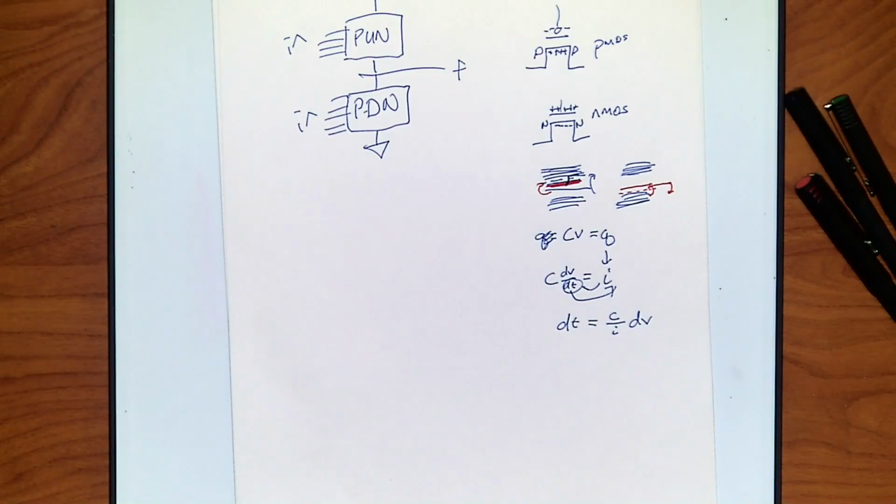Sounds like a weird question, but I want to get something. I don't want to use P1 transistors. Then I use... okay. What's its disadvantage? Yeah, it doesn't transfer the power. So I'm going to get a huge drop on these. It's very inefficient, so I really don't like that. That means I'm generating more heat for no benefit, because I'm going to get, somewhere, probably a loss of a volt or so on this. It's just not my favorite, right? So can't really use that.